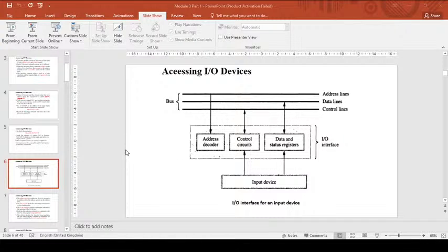So what does this instruction do? Compare. Compare means subtract: destination minus source. So this is the source, this is the destination. The entered character is in R1, that forms the destination. So destination minus source. If the result is 0, that means both are the same. If both are the same, the entered character is the carriage return, and the end of line is reached. Then this particular condition becomes false.